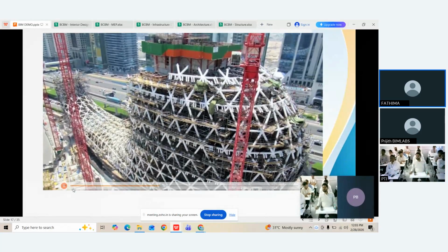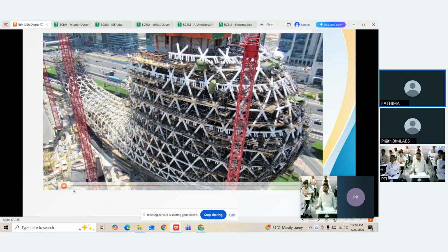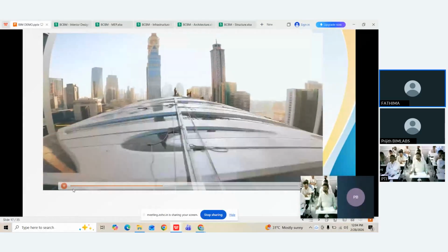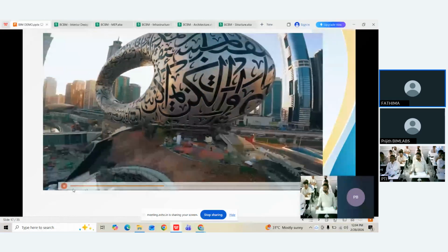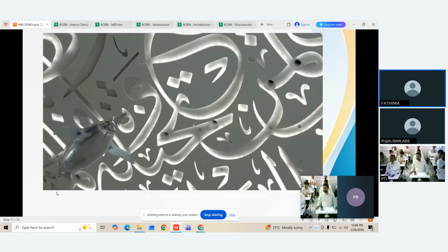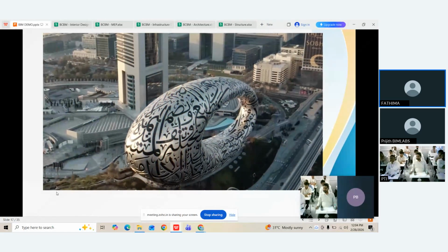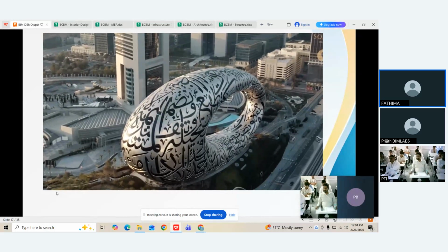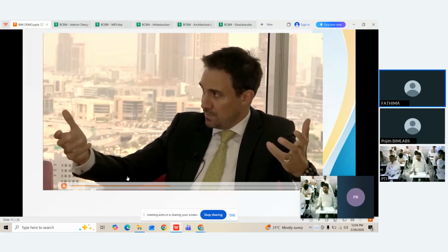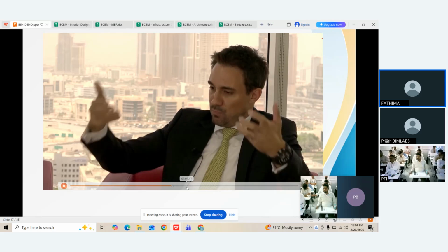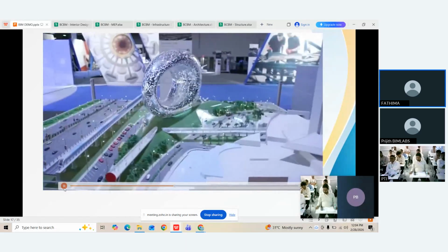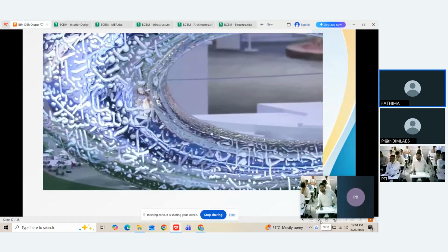Before starting construction, BAM Higgs and Hill and Arup Engineering performed a construction sequencing study and connection design for the structure, taking into account shifting stresses and loads throughout erection. A lot of member alterations occurred due to the construction sequencing analysis, according to Fowley. Because the diagrid had been optimized and modeled, none of the steel members were changed on this project, he claims. We used previous project learning and established tools to solve difficulties we knew existed, so we wouldn't have to confront them again.